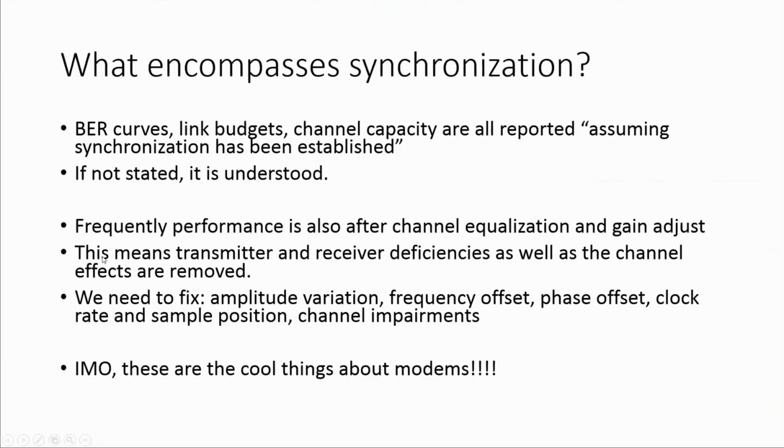So what this means is that these guys showing these curves assume that all the transmitter receiver deficiencies and the channel effects have been removed. Then I can show you these curves. So we need to fix all these things: amplitude variation, frequency offset, phase offset, clock rate, and sample position, and channel impairments. This is what synchronization is all about. Fixing all the things so that these things will work. To me, this is what's cool. A lot of people really like coding, but I think fixing these things is the most interesting thing about modems. Synchronization.